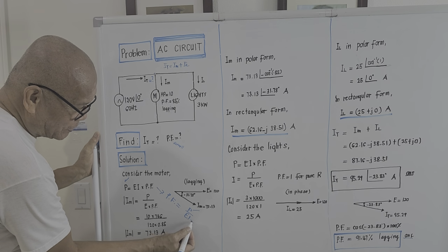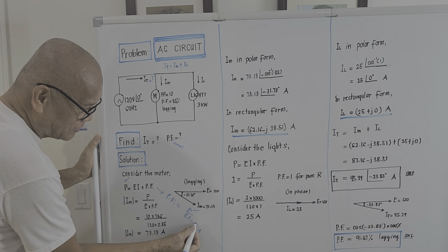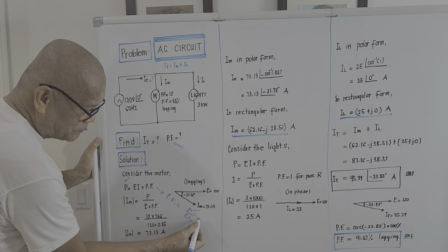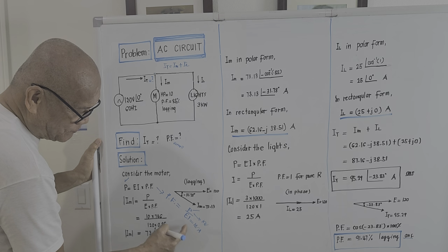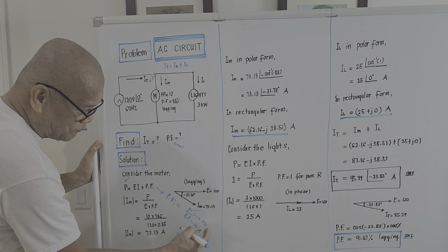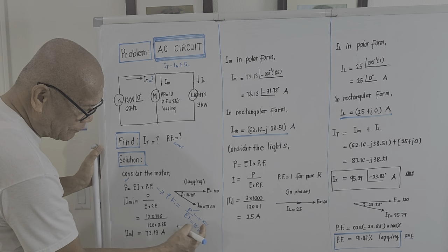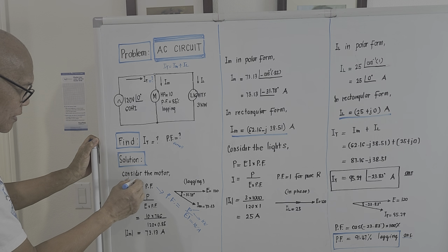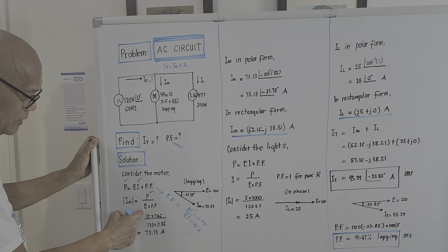EI is actually the volt ampere, or usually you always hear that as kVA. So if EI is kVA, this should be kilowatt, right? But if EI is just simply volt ampere, true power will just be simply watts. But if EI will be kVA, true power will be kilowatt. So in here, if we try to compute for current, it will be true power over E times power factor.